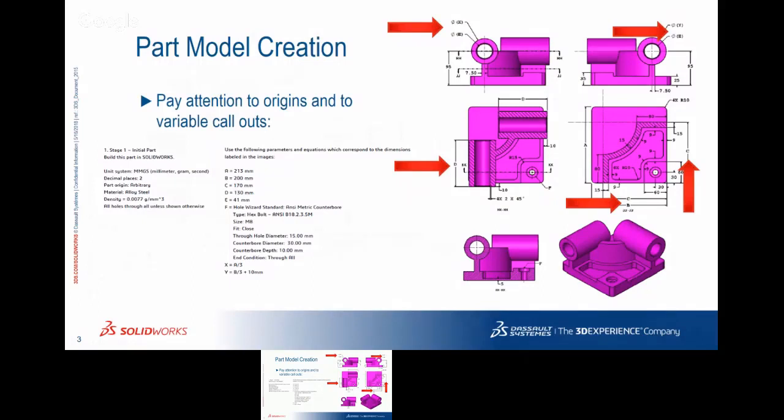And in my experience with this model, it's easier to wait and do the fillets at the end. So the next thing I'm going to do is build this vertical wall here. And you can see we have the shape here. It's basically all called out in this drawing view. You can see the 80 millimeters with 15 millimeter offset, and then the 80 millimeters over here, and basically 15 millimeters wide. So in this case, this 15 millimeters is called out three times.